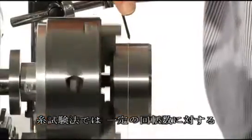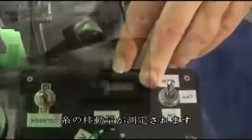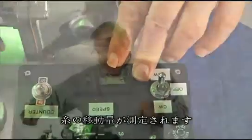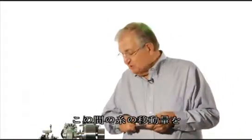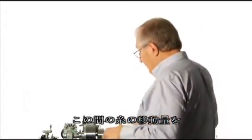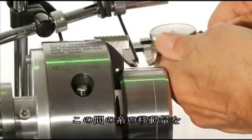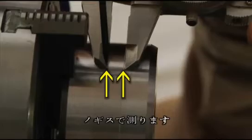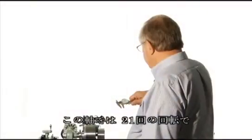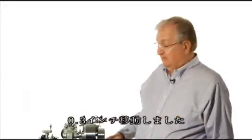So what we do is we run this string on the shaft, and you can see it's traveling for a specified number of rotations. Now that's 21 rotations on the shaft. And so by taking the pair of verniers and measuring the distance that the string traveled from that pointer to the finish, I've got there 300 thousandths, and I've gone like 21 rotations.